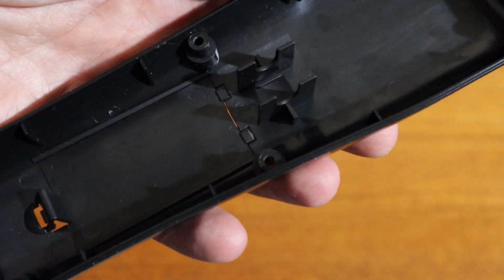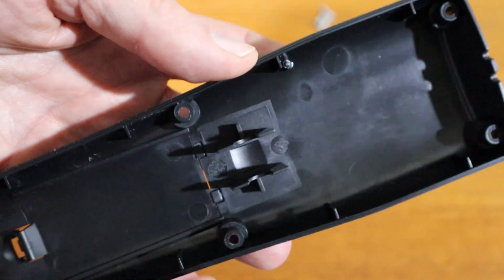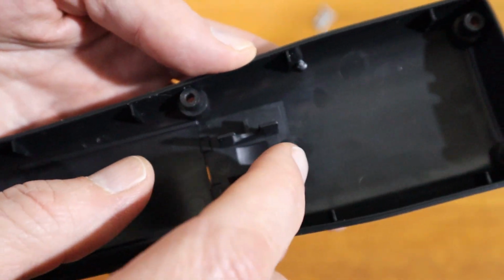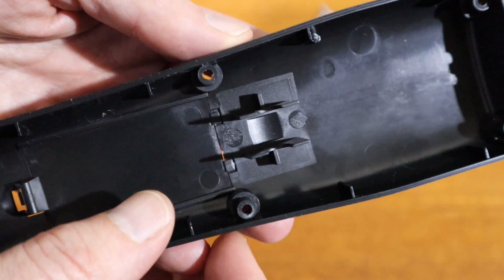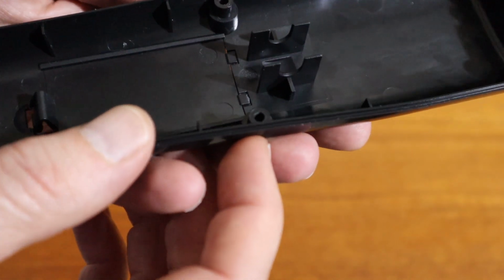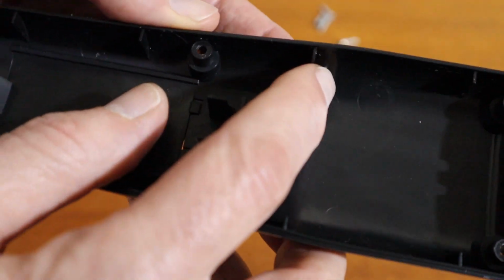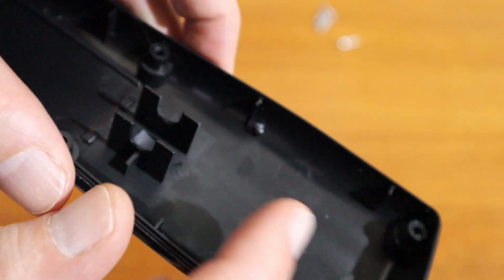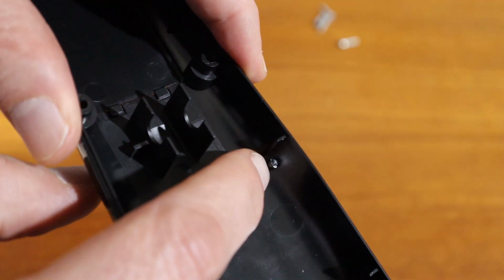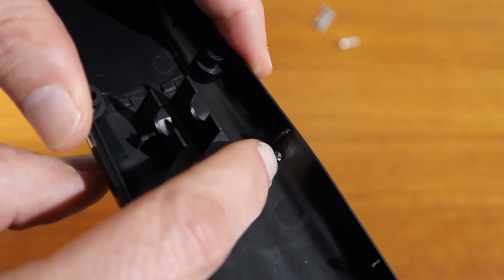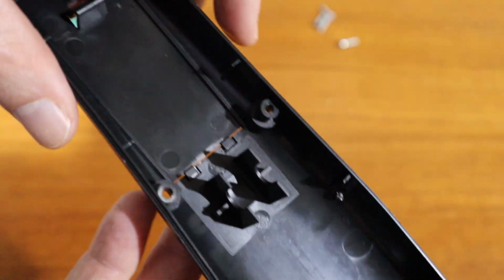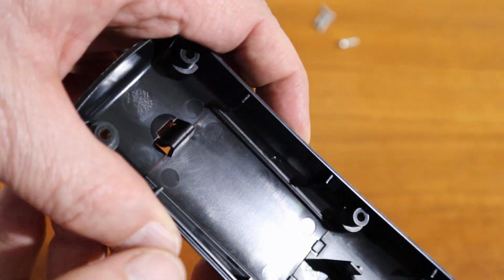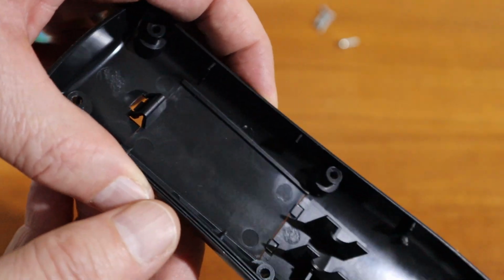Let's take a look at some of the details in here. You can see there are some marks right there and there. That's where the ejector pins push out. And if we look carefully, see if I can find it, here it is. So this right here, I'll try to get a better picture of that. This right here is where the plastic is injected. That's where we have the submarine gate. And then the rest is pretty straightforward. Again, we have some ejector pins there, which is what pushes it out of the mold.